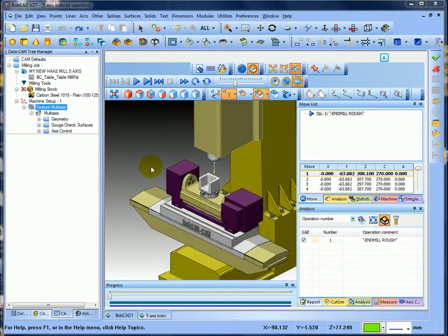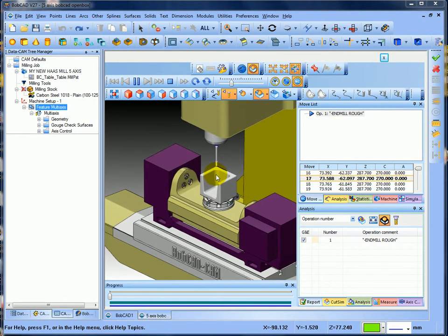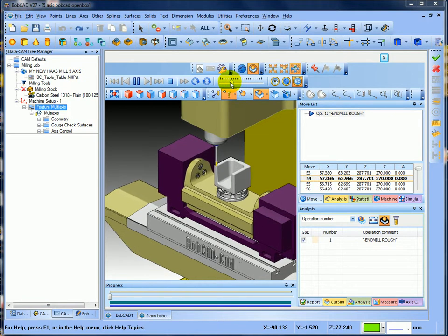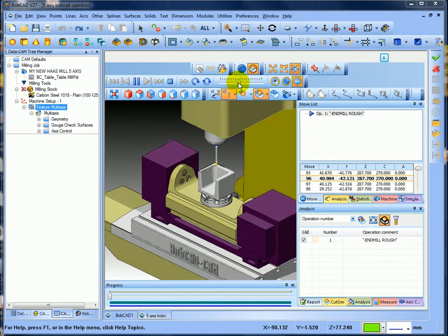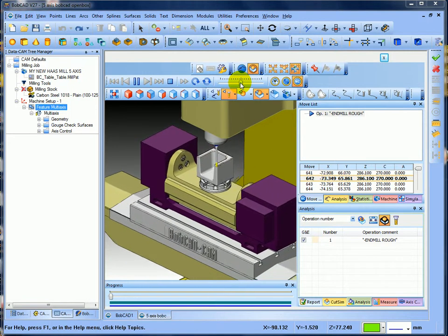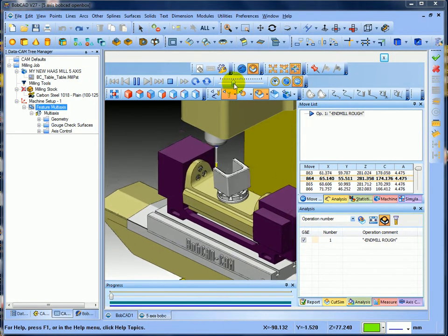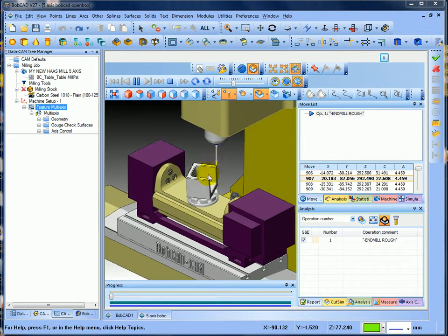It's within the package. So all I'm going to do is simulate this, but I'm going to tell it I want to cut this shape, but I want to also use the 5-axis to machine it with. So if we just run the toolpath, that's this piece of stock at the moment on top. If I just speed the process up, then you'll see the 5-axis come into play. Now you can see I'm now spinning the job round in 5-axis.